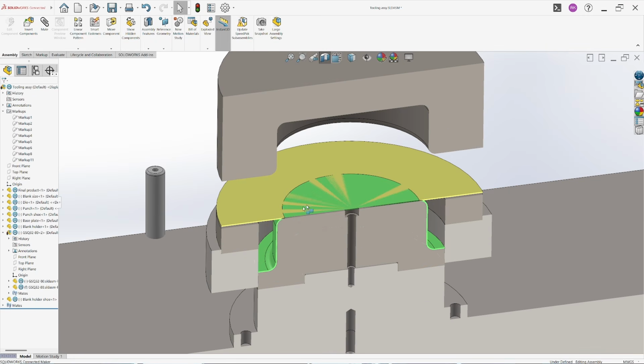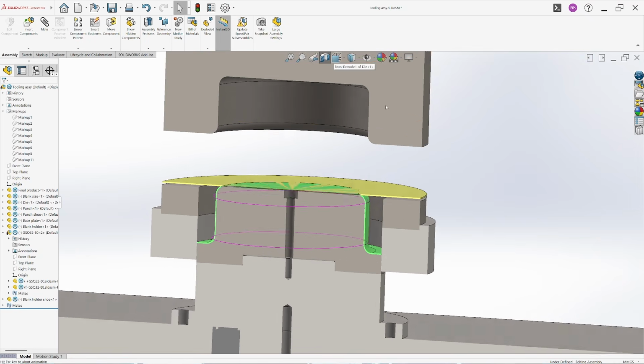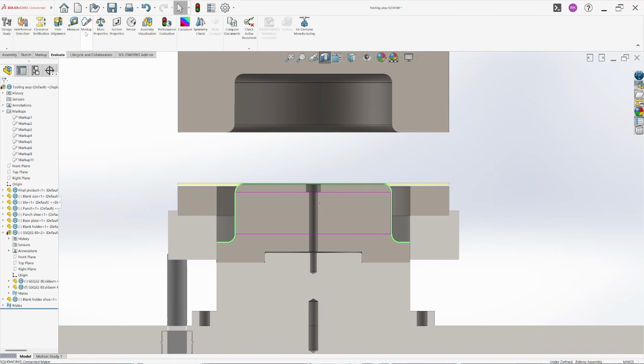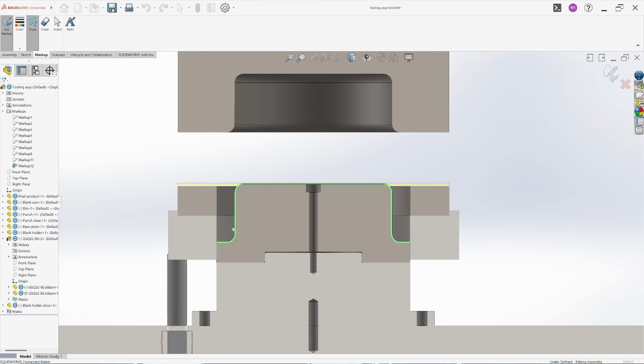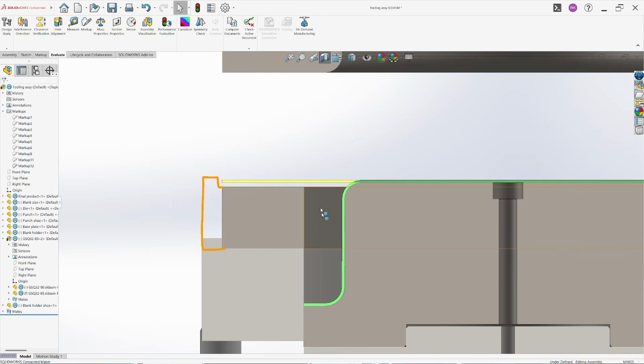How will we be sure that we have placed our blank into position, because there is no guidance, right? So what we can do is add a step for placement of the blank over the blank holder plate. To do that, we will need to add a guide, something like this, right? So we will be able to put our blank plate into a circular cavity. So let's try to add this step into the blank holder.